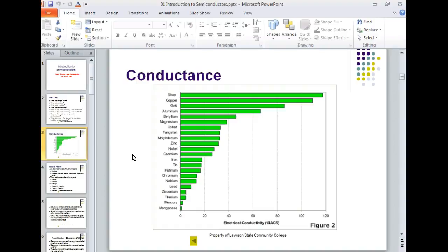Some of these we actually use inside heaters. So if I'm going to heat with a piece of wire, we want it to act like a resistor, right? So we'll use like nickel or tungsten. Tungsten is used a lot as a heater element because it has a bigger R, and you get heat when you run current. The filaments on incandescent lights are tungsten. So even though they're considered to be conductors, they still have a pretty good deal of resistance, so they get pretty hot when you heat them up, right?